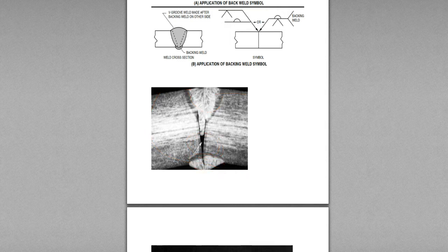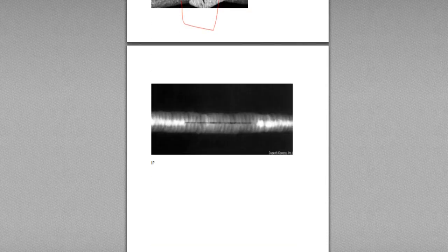If you go to API 1104, section 11.4, this picture shown is kind of ICP, inadequate or incomplete cross penetration, but it's kind of IP, inadequate penetration. And if you radiograph it, then the RT film shows like this. Here nothing, no filling. This is IP.